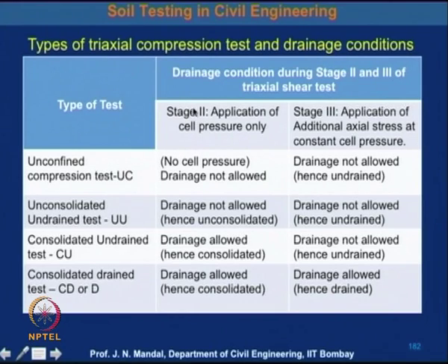After the preparation of the sample, you have to apply the cell pressure, that is stage 2. The first stage is the preparation of the sample, and the second stage is the application of cell pressure only. Because it is unconfined, there should be no cell pressure, and drainage is not allowed.